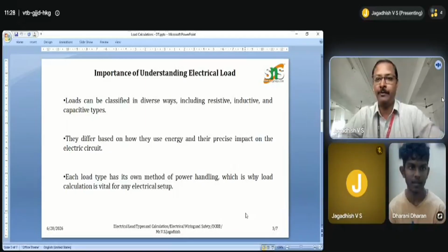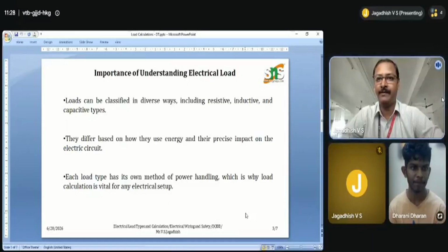Thank you for explaining. I would like to add a few more points on what a resistive load is. A resistive load directly converts the available power into another kind of energy, for example light or heat. A simple fluorescent lamp or bulb converts the electrical energy it consumes into light. Water heaters and induction stoves consume energy and convert it into heat. We are converting one form into another form, which is called a resistive type of load.